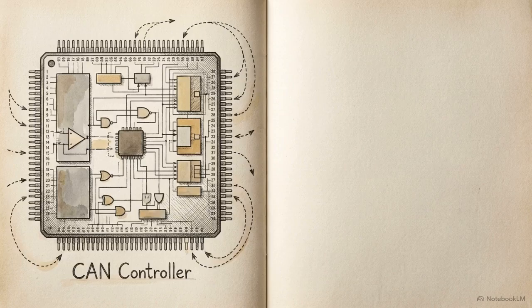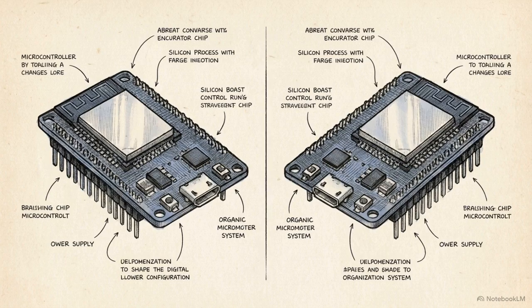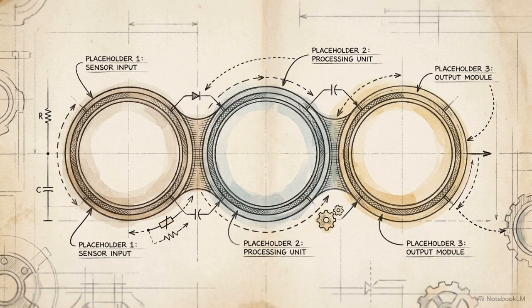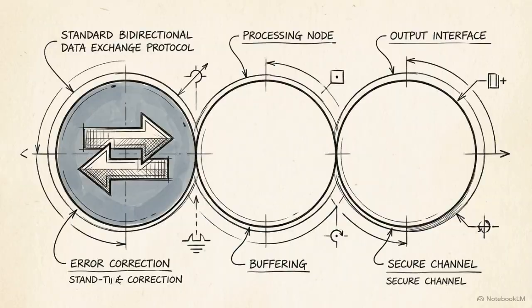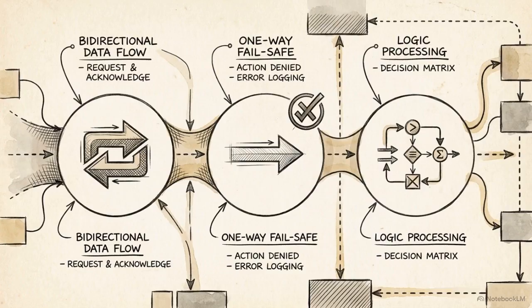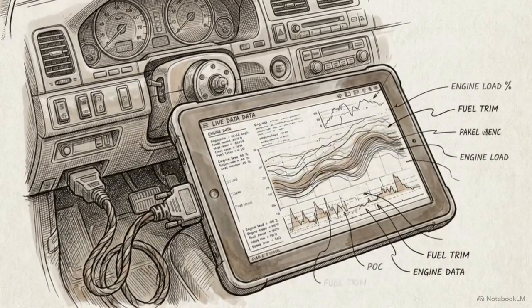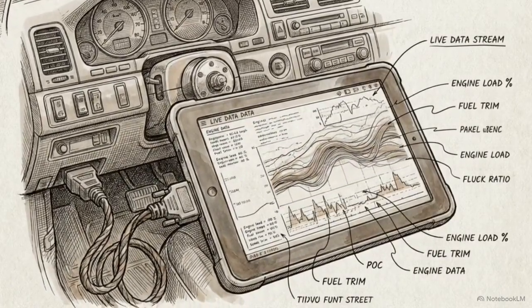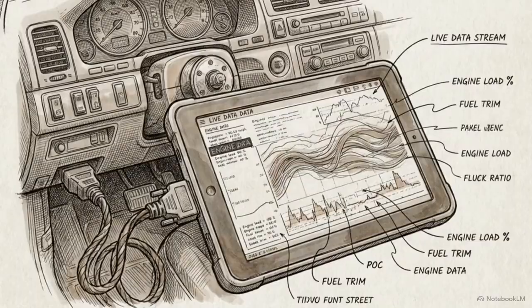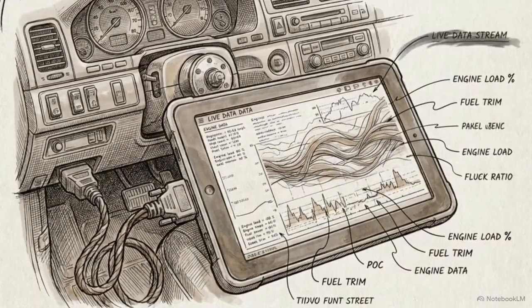The ESP32 actually has a built-in CAN controller, but Espressif refers to it as the TWAI, or Two-Wire Automotive Interface. For our purposes, TWAI and CAN are identical. The TWAI controller supports 3 modes. First is normal mode, second, no ACK mode, and third, listen-only mode. Listen-only mode is crucial, allowing the controller to passively read data without transmitting, keeping live vehicle networks perfectly safe.